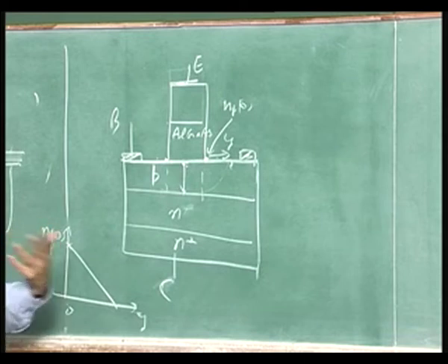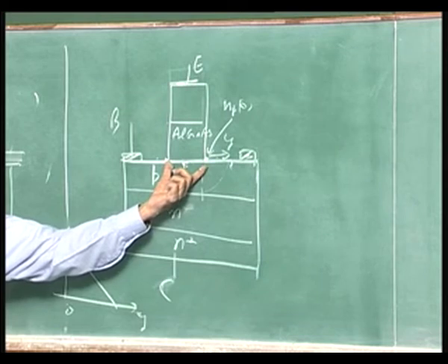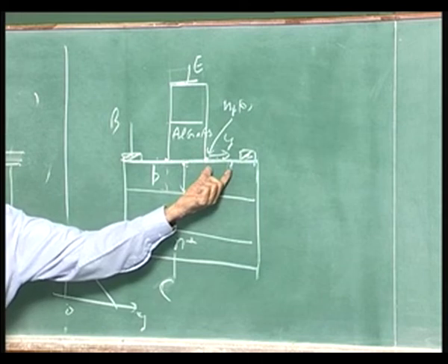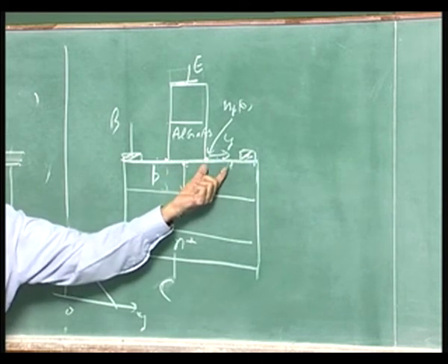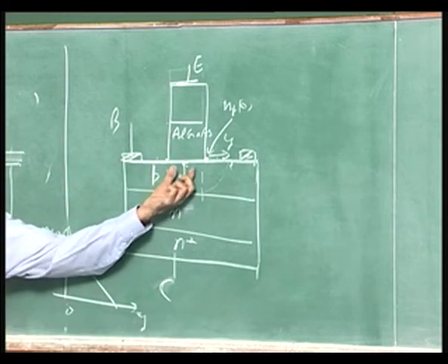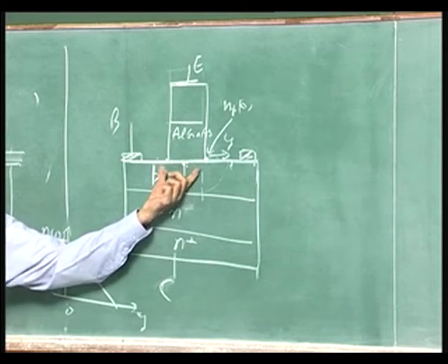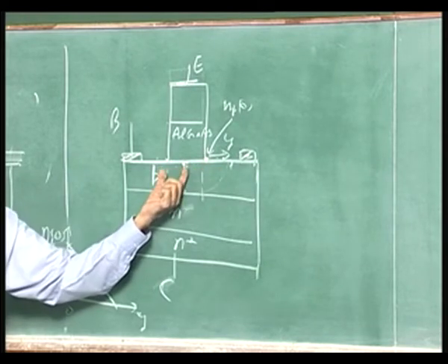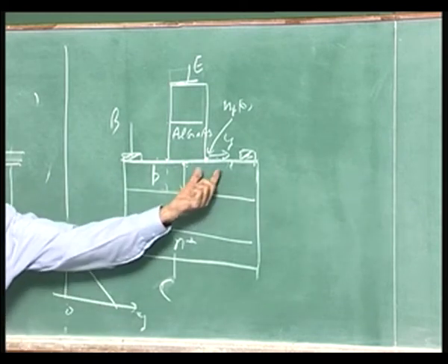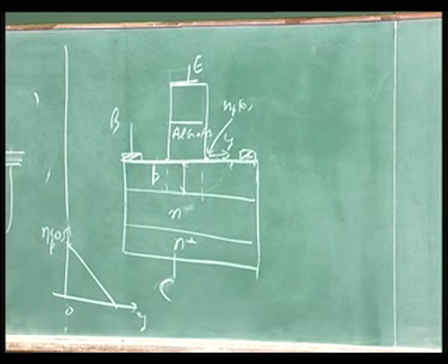Supposing it is a circular emitter of radius RE, pi r squared is the emitter area, and this area will be pi (r plus that width) squared minus pi r squared. You can see now, if this area becomes larger and larger, this area compared to that will become smaller, because this is fixed by that width. For a given base width, this area is fixed by that. So, you will see the equations much more clearly.